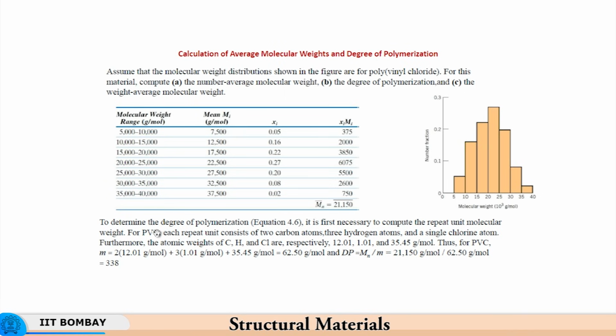So now when you mix these polymers or macromolecules of different molecular weights, it correlates with the kind of strength you are looking for in the final product you make. It has to do with the final amount of strength that you want to generate in the application, and therefore you would select the molecular weights depending on their mechanical properties as well as the melting points of each, and accordingly decide the processing conditions.